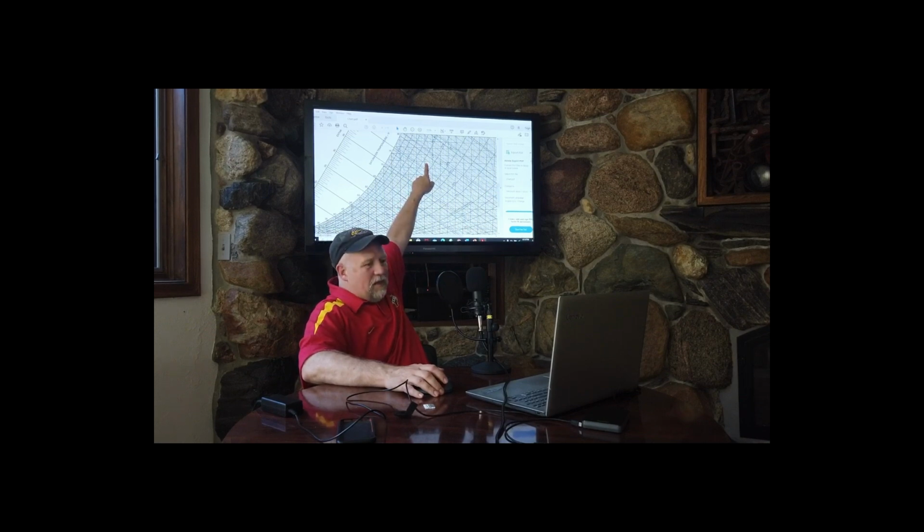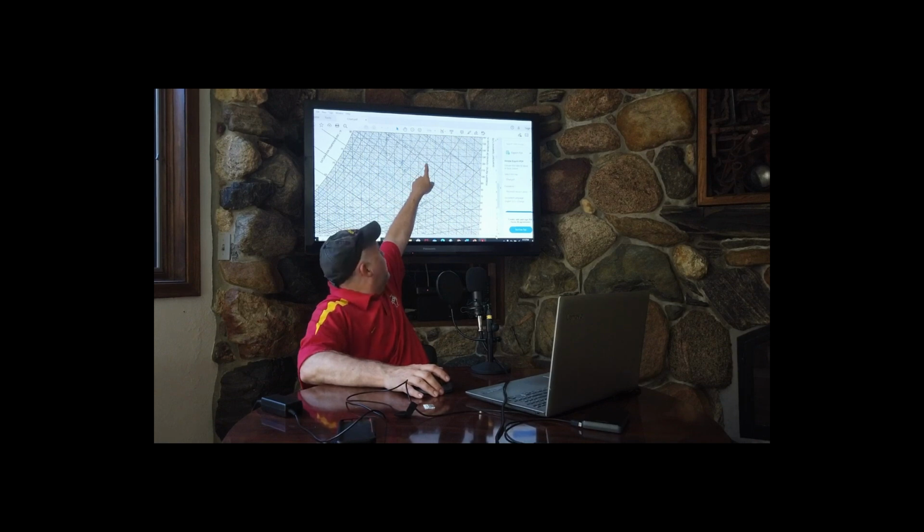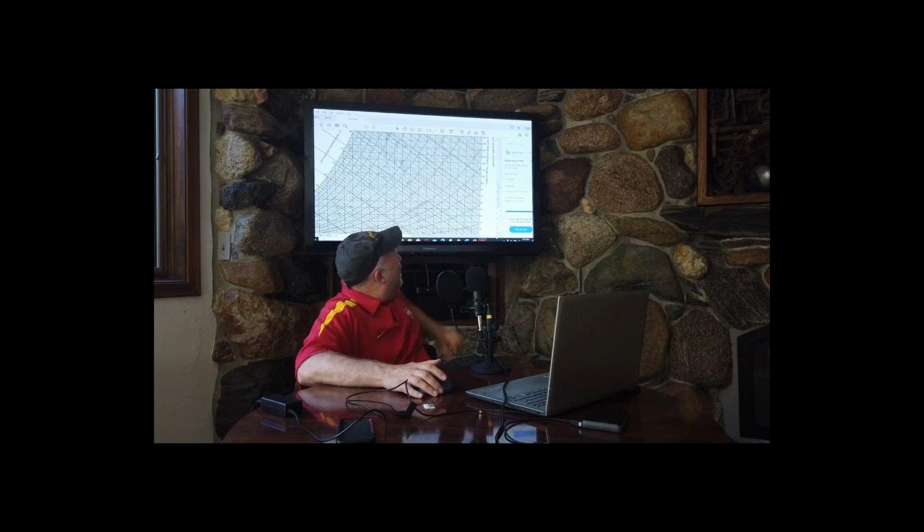And if we pull that out to the side, you're going to find a humidity ratio of right about, let's see here, I believe it's right about 116 or so grains of moisture. I'm just using my finger on a screen, so I'm not exact on that, but I want you to look at it exactly. Go out there and find the humidity ratio in grains, and then you can also find the dew point temperature.